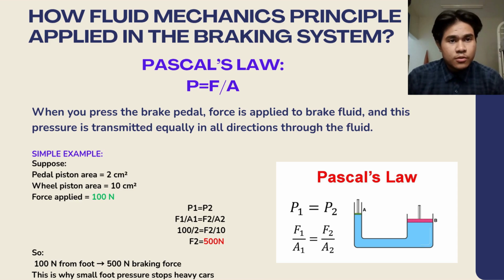My name is Muhammad Ridwan bin Asmizam, and I'm going to continue on how fluid mechanics principles apply in the braking system. So basically, the braking system uses Pascal's law, which is P equals F per A. When you press the brake pedal, the force is applied to the brake fluid, and this pressure is transmitted equally in all directions through the fluid.